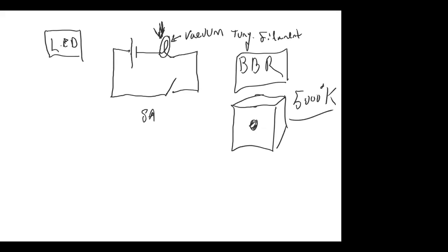And this is a real thing. People need to be exposed to the 5,000 degree Kelvin light because they need that daylight. It's particularly onerous for people who have to be on lockdown during COVID because they don't get out much. And this can create its own sort of depression. And so that's a big deal. And when people shop for fluorescent bulbs, they go for this color temperature.